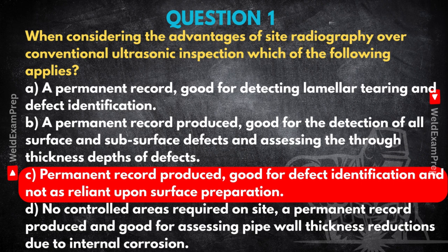It's huge, actually. With radiography, you get a physical film or a digital image. It's tangible evidence. Unlike ultrasonic testing, where the data can be, well, a bit transient unless you're meticulously recording every signal, the radiograph is a snapshot. You can archive it, review it later, use it for audits, quality checks, even track if a defect changes over time. For things like compliance or documentation, that's gold. Right, like having actual proof you can file away.